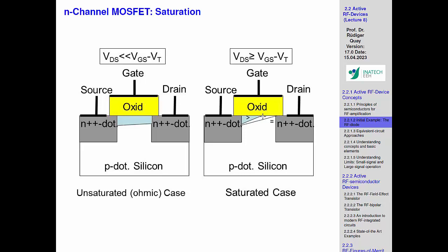That's similar. What we haven't declared is that all these voltages have to be seen relative to a certain threshold. This threshold is introduced because the definition of when this is happening at a positive or a negative voltage is not so clear. This is strongly structure dependent. So the effect will always take place, but the question is, does it necessarily happen around 0 volts, or is it because of some charges somewhere at -1 volt or +1 volt? That is still under debate. So that's why we are introducing the threshold.